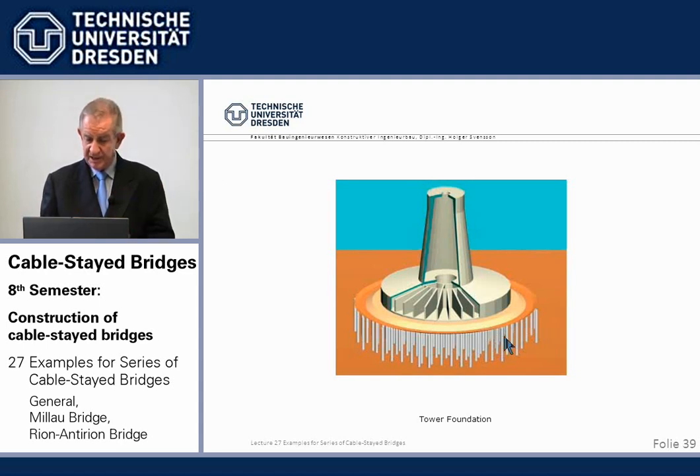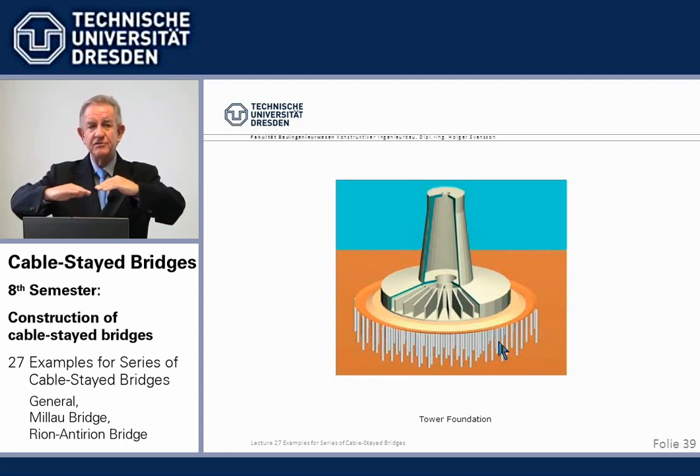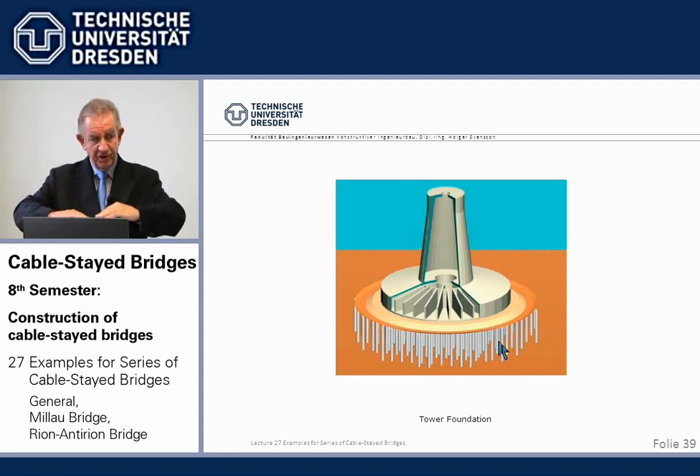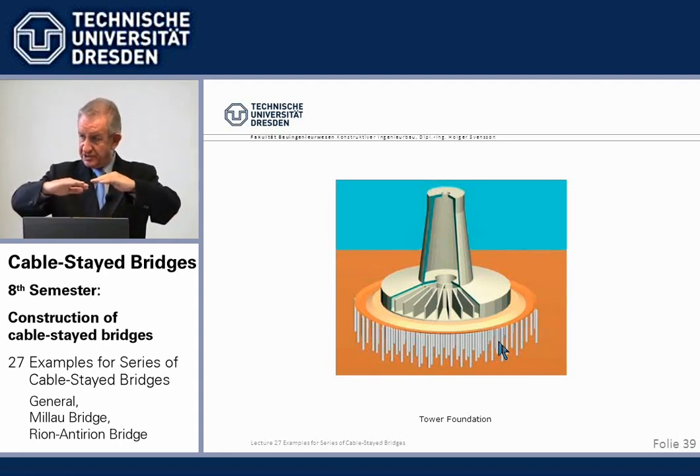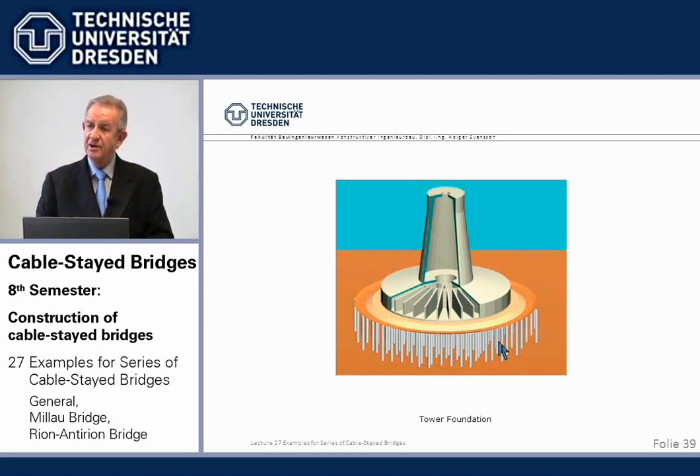And then underneath this layer of differentiated layer of gravel, there are steel piles, but they end at the top of the soil. So they are not piled foundations, but they just reinforce the soil underneath, but they have no connection to the foundation itself, not a piled foundation. It's a reinforced earth in effect.